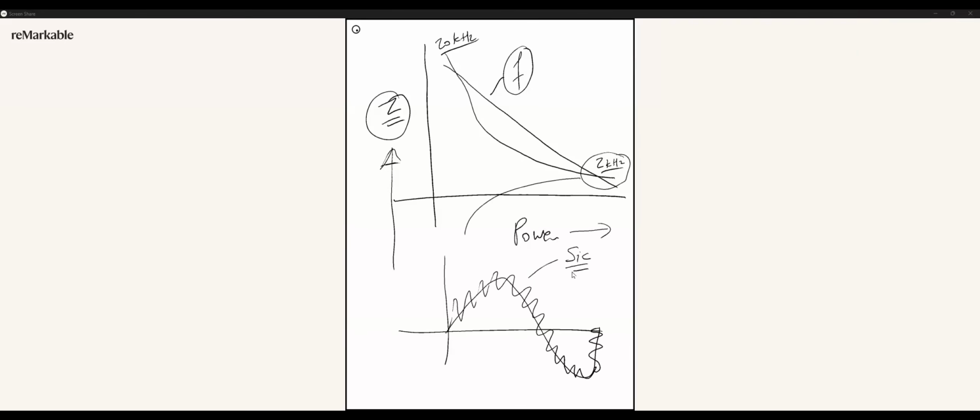Anyway, for higher power drives, we cannot go for higher switching frequency because the switching losses will be considerably on the higher side. Yes, so that is also the case. We don't even go for 2 kilohertz. It's below that even, 500 to 1.5. Yeah, I've seen lower than 2 kilohertz as well. Yeah, in railway drives,